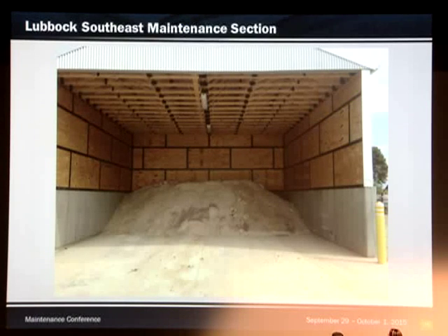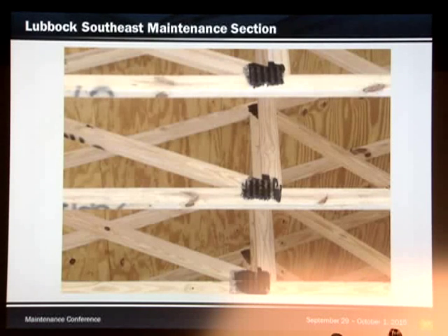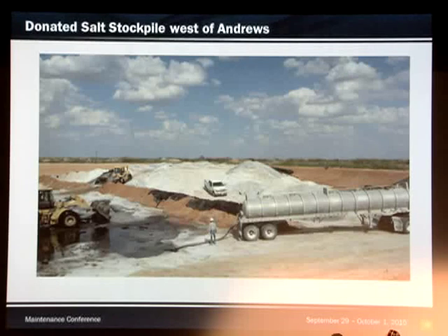These are just a couple of shots of some of the latest salt bins that have been built. These have lumber trusses in the roof, with all the metal connections, the connection plates. I can't remember what they call those. I'm a little worried about whether they'll hold up, but hopefully they will. It's amazing how, even though you've got a metal truss 14 feet up in the air over salt, it still tends to corrode away. So we'll see how these hold up.